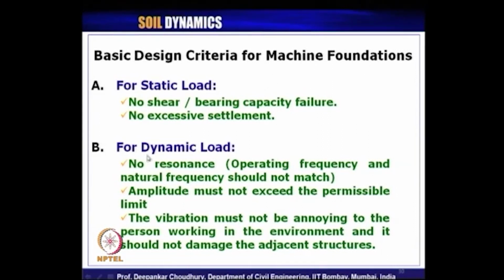So, in that check for dynamic load, we have to check for 3 criteria. These are the 3 major points. What are those? The first one is no resonance condition. Of course, under the dynamic load, your foundation should not resonate, right.